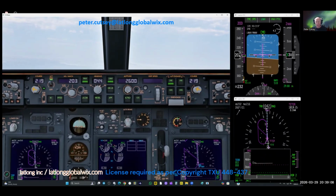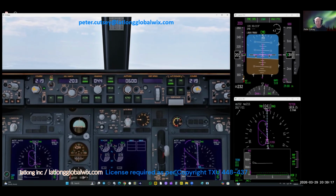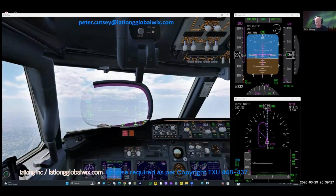So we'll set a lower altitude now in the window for visual approach, 500 feet, and 518, but run it up to 600 for reference. Follow your company SOPs, of course.